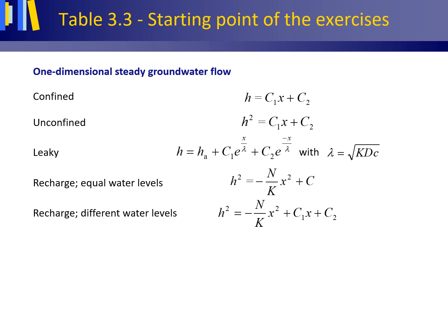As advice for making proper calculations, do not round off any of your in-between results, especially so for the C1 and C2 values of a leaky aquifer. As best practice, use symbols such as h0, hL, L, etc. instead of their known values in your calculations right up until the end. That is, insert their values at the end. Even better, make use of carefully built up spreadsheets for your calculations.